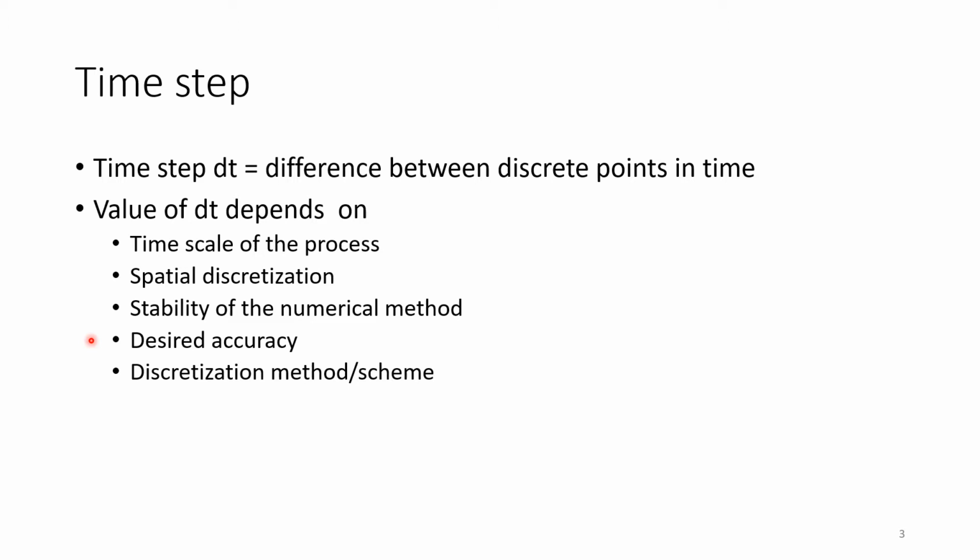This is, of course, usually valid the smaller your time step is, because you're linearizing only about a very small time frame, and then for the next time frame you can change the inclination of your linear approximation, for example. And then also, of course, the numerical method itself, the solution process, and so on will determine your time step, or the maximum time step. Again, it's a maximum time step to achieve stability and accuracy.